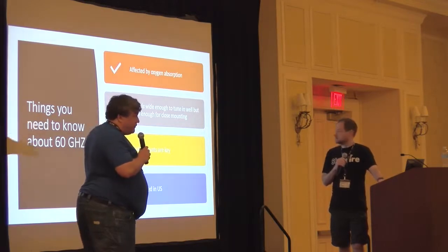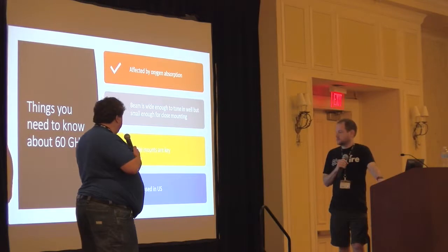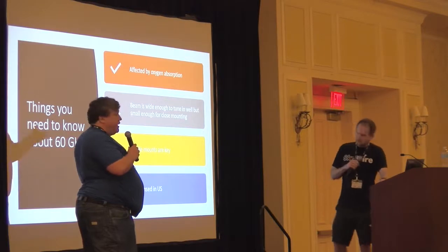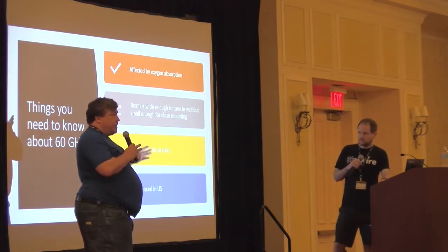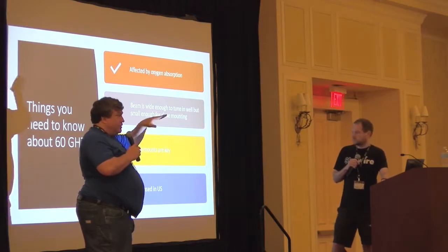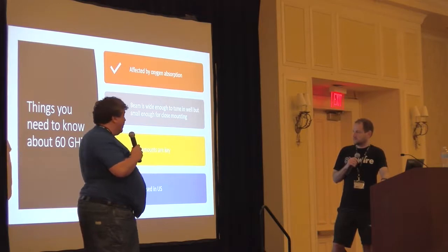Stable mounts are key for anything in this frequency range. It's unlicensed in the U.S., so you can deploy it pretty much wherever. One of the nice things about the beam width being so tight is you can stack these on top of each other. You can have several pointing off to various places, and you're going to mitigate your self interference by just using 60 gig.